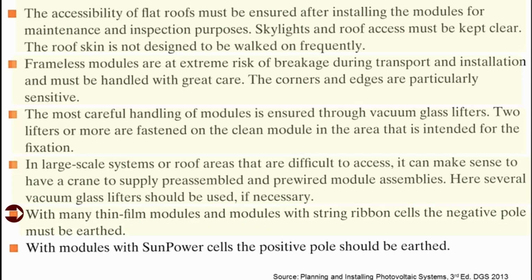With many thin film modules and modules with string ribbon cells, the negative poles must be earthed. Just consider then the instructions by the manufacturer. Also with SunPower modules, which are N-type modules, the positive poles must be earthed.